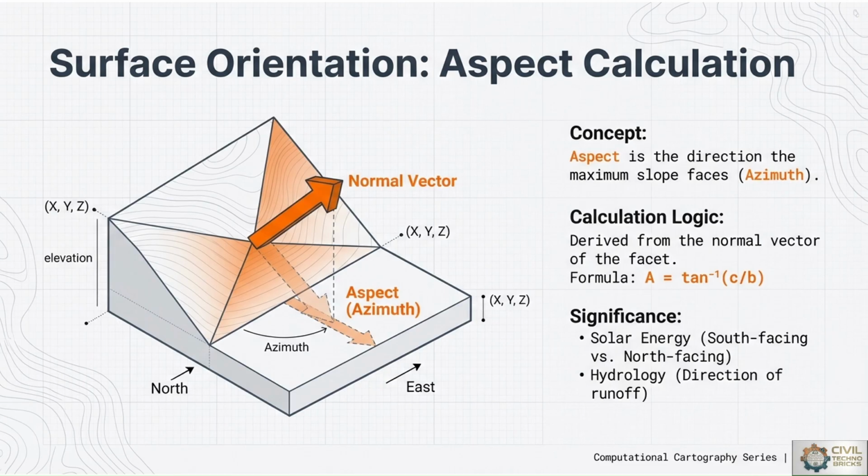So surface orientation is most important for choosing between the digital elevation model and a triangular irregular network, which depends on engineering objectives. Raster digital elevation models are data heavy but easy to process for regional analysis like flood modeling or regional planning. TINs are most efficient because they use more points in complex terrain and fewer points in flat areas, saving storage space without losing details.